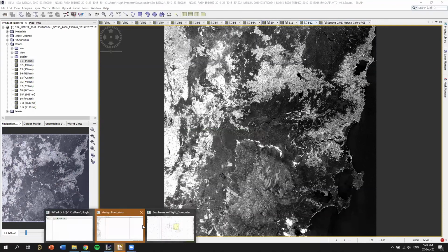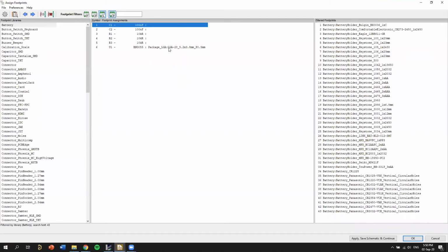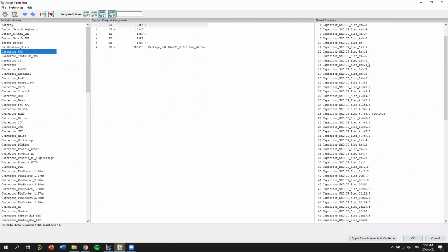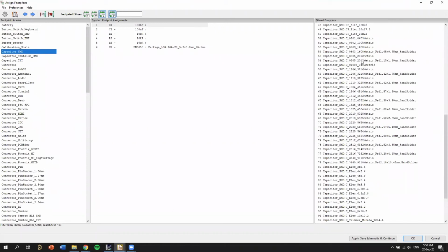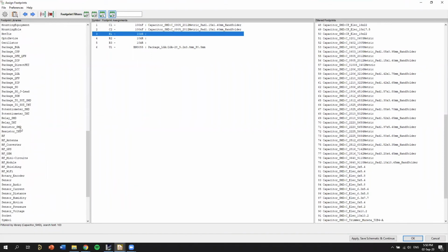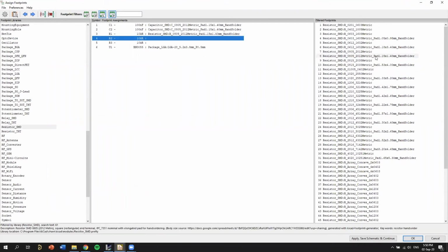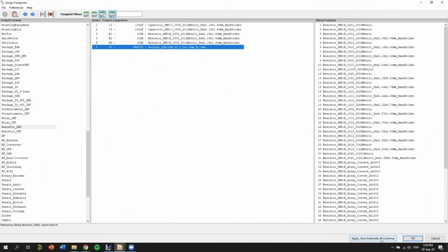All right, beautiful. So Banner already has the right package specified. So let's just chuck on some basic capacitors, capacitor, SMD. I like 0805, so I'm going to stick with that. 0805 on those, and then we'll go chuck our resistor, 0805 hand solder.